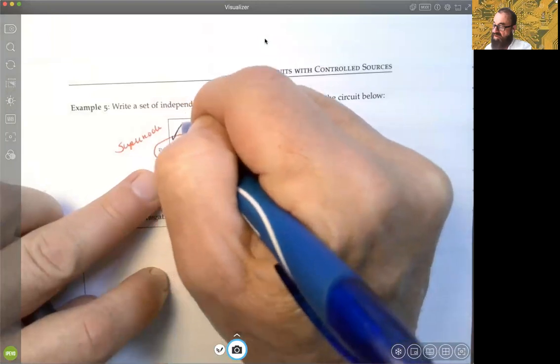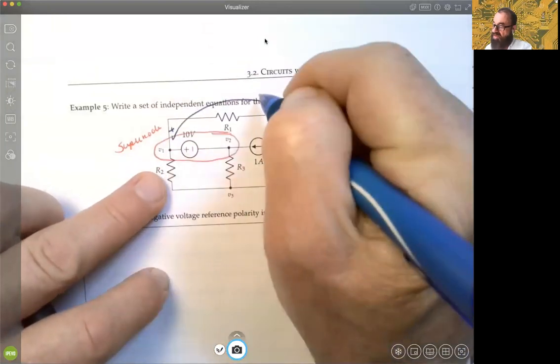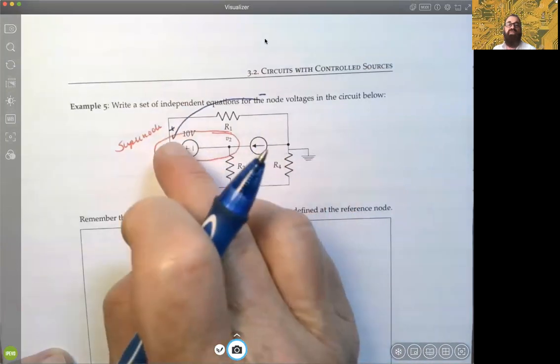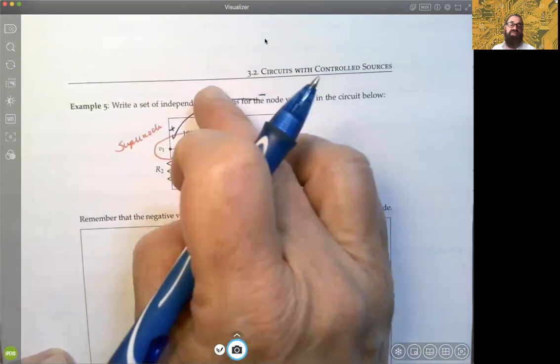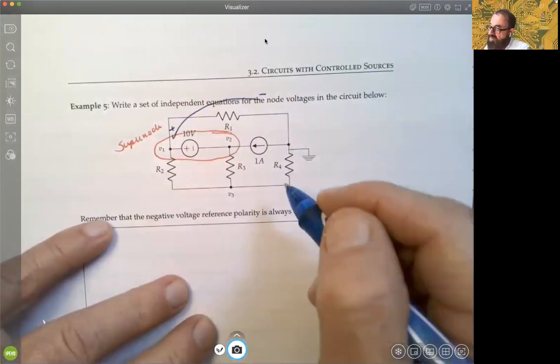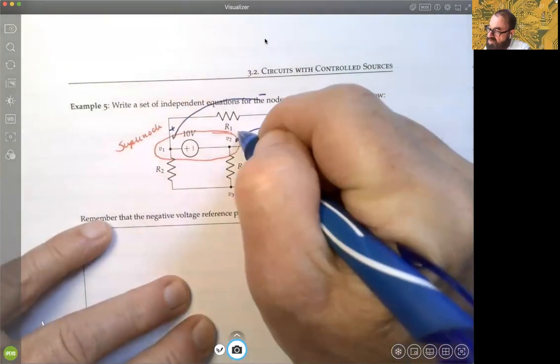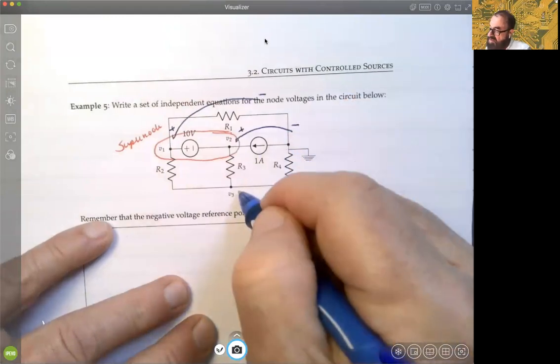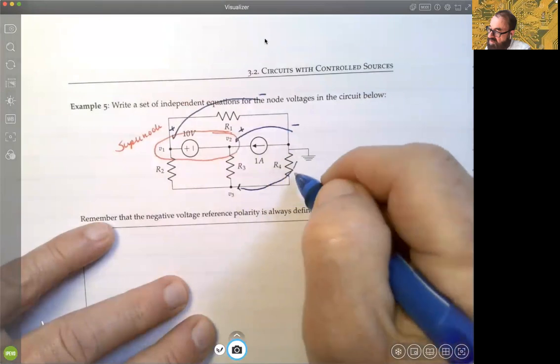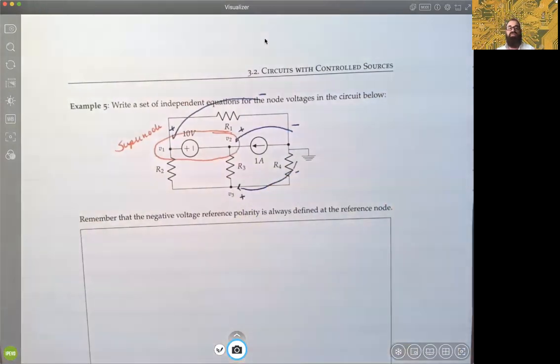And this voltage arrow for that V1, you're plus here and minus there. So if you're doing KVL and you come into the top of the arrow, you're going to be plus. If you're coming this direction, you're going to be minus for that nodal voltage. Same thing for V2. I'm just drawing some polarity arrows here. Same thing for V3, okay? In terms of minus and plus. So it's just good to get the polarities for your nodal voltages straight, depending upon where your reference node is.